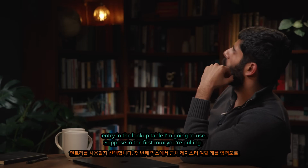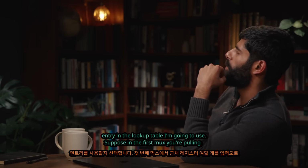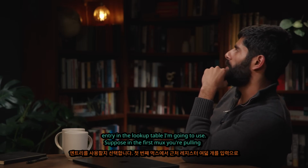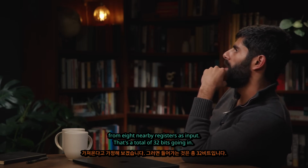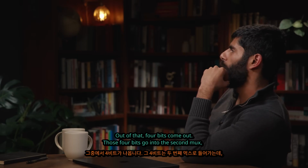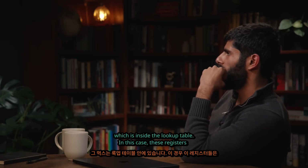Right, okay. And just to make sure, suppose in the first mux, you're pulling from 8 nearby registers as input. Mm-hmm. And so that's a total of 32 bits going in. And then out of that, 4 bits come out. Those 4 bits go into the second mux, which is inside the lookup table.